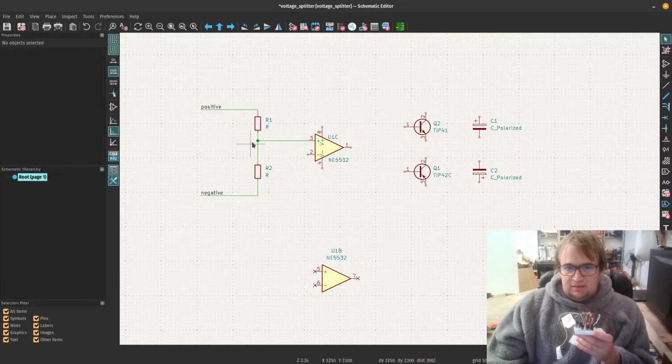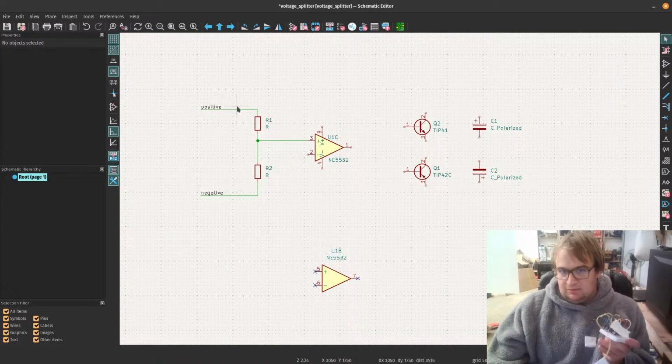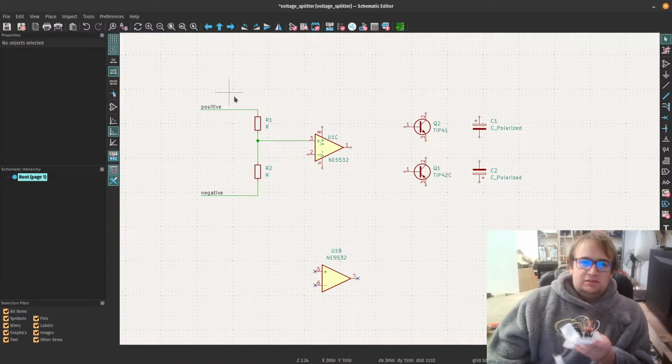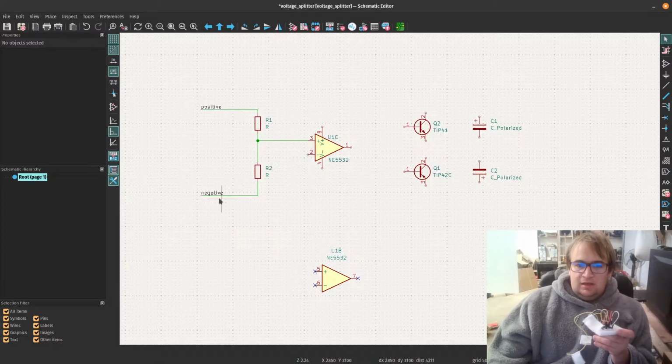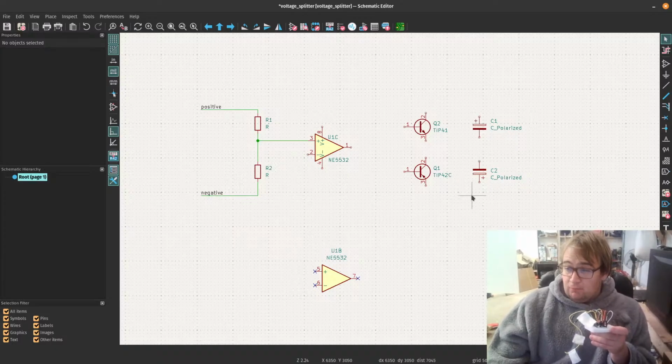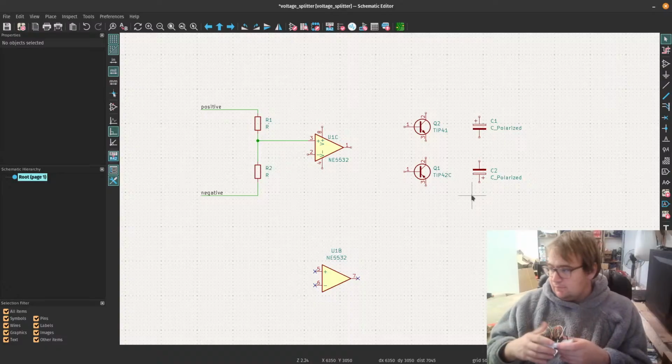That means these two voltages here will want to be in the middle of whatever voltage differential we apply here. And the way they'll do that when we have the negative in the middle is it will basically make this one like V divided by 2. So in my case, I set it at 15 volts, V equals 15 volts, so then it was 7.5 volts here, and minus 7.5 volts on this side.